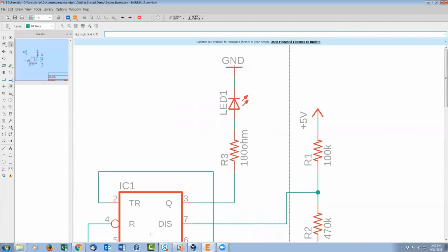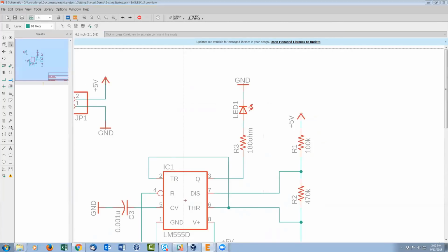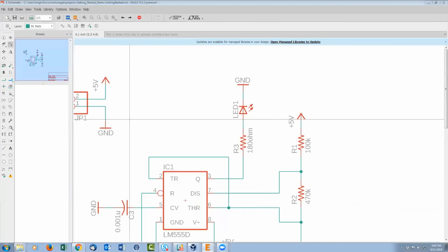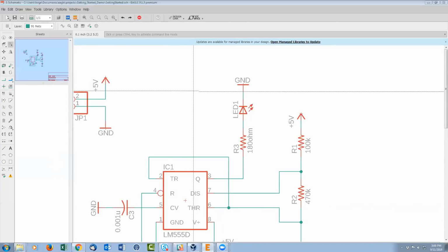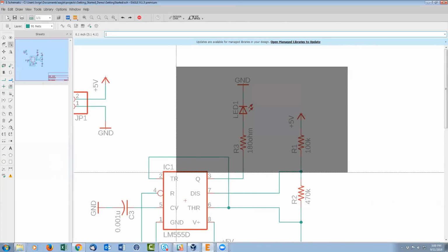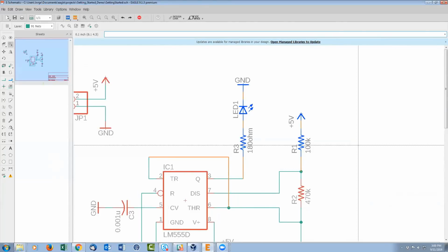There. Okay. There's a question on the Q&A that I'm seeing. Did you do a multiple selection? In Eagle, there's three main ways to do multiple selection. They all involve the group command. One way is just left click and drag. It'll form this selection rectangle. That's one way. It's the broadest.